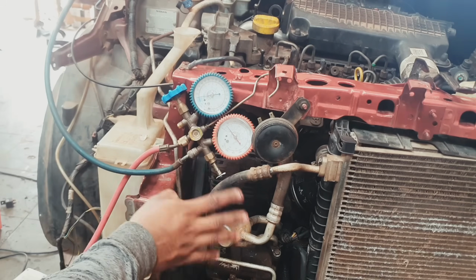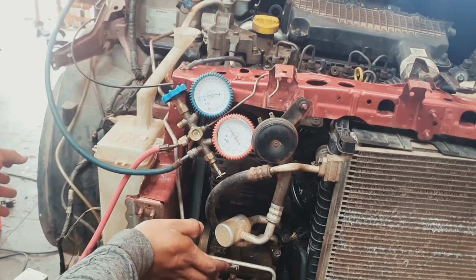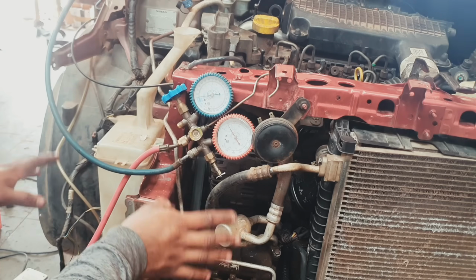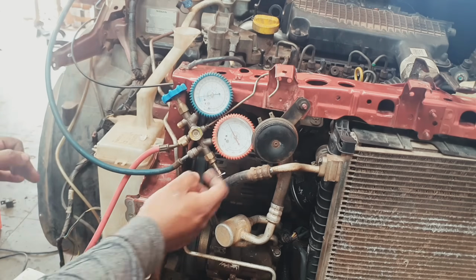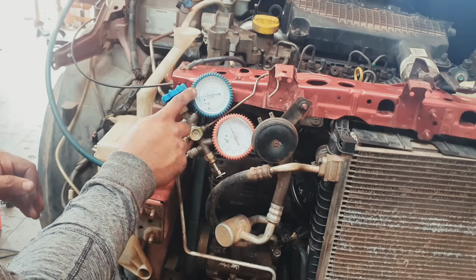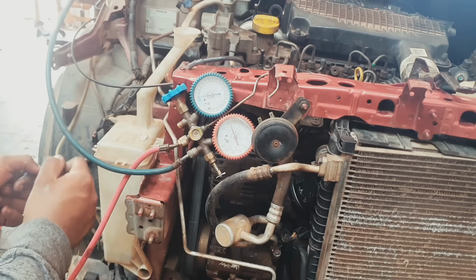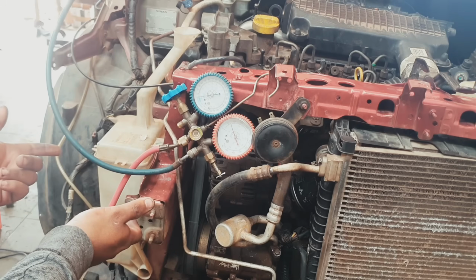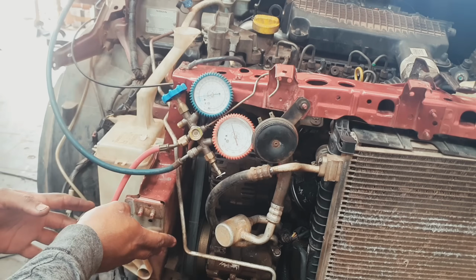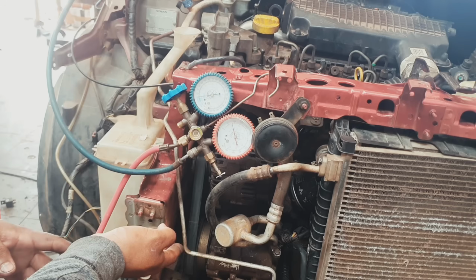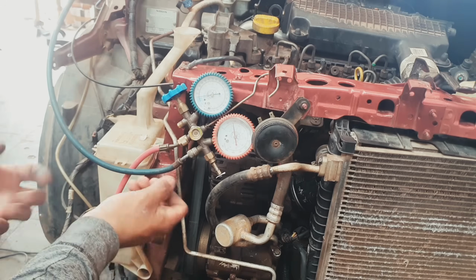So as this fills, I'll tell you what the low and high of operating are. In a small AC system, the average high running pressure is about 250 psi, so it is up to 250 psi, and low should be around 20 psi. I'll explain why. Earlier I explained the AC system in the chart, but that was just basic. In the next video, if you are interested in this part, I will explain in detail how the AC system works.